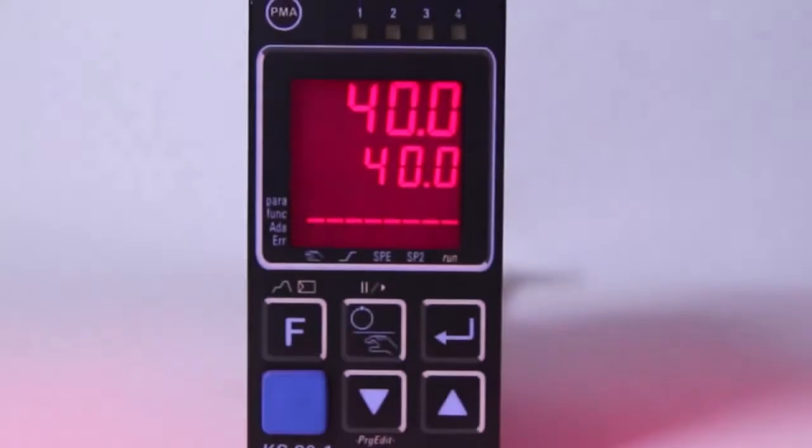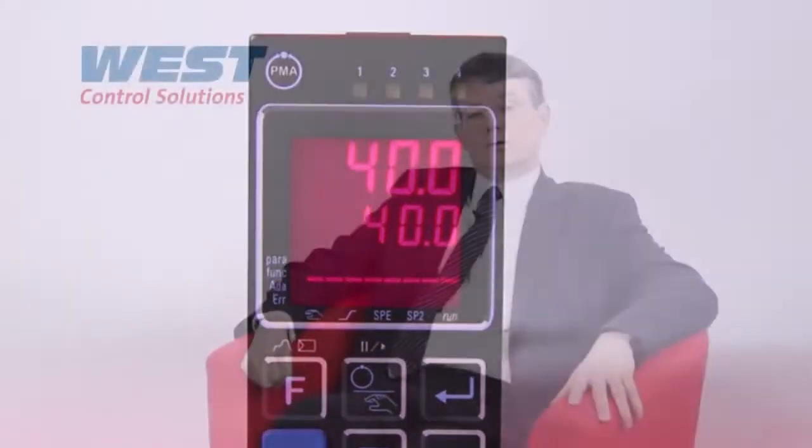Similarly, if the cycle time was set to 64 seconds and it was on for 16 and off for 48, this would also be 25% of power. However, the number of switching cycles would be reduced considerably, so you can see how the user can control how often their devices are switched.